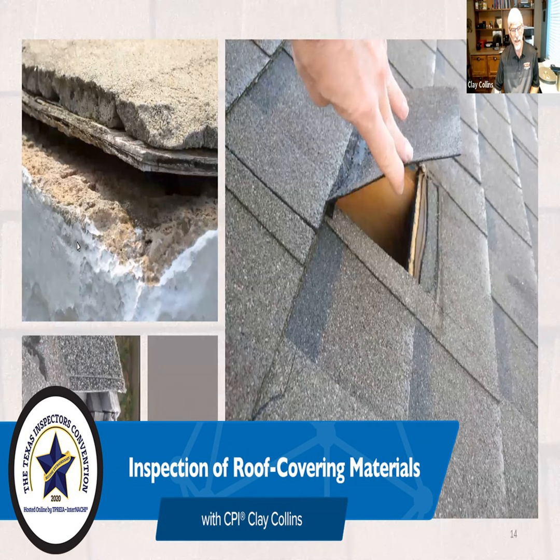I inspected the attic from the top of the stairway, from the scuttle opening, or from the service passage and service decking. And you make sure that you don't just casually look. You get that high-powered flashlight and you look down into those eaves, because it's down in those eaves that you're likely to see the biggest problem.